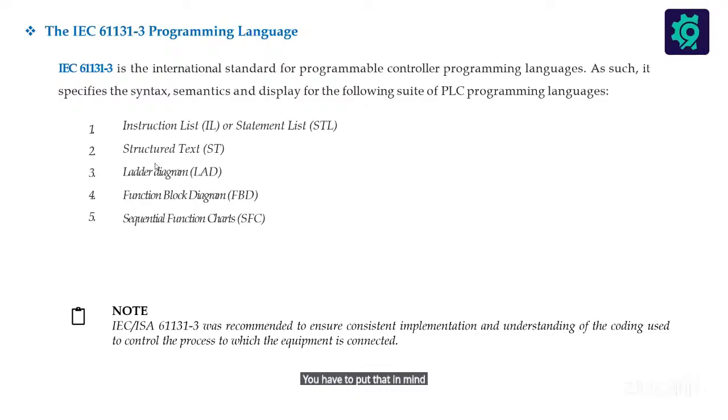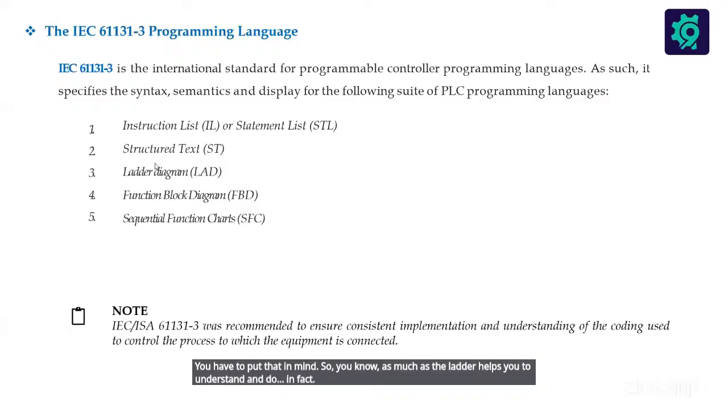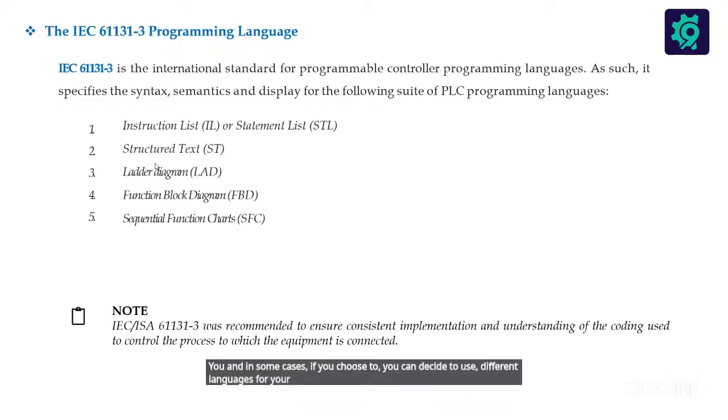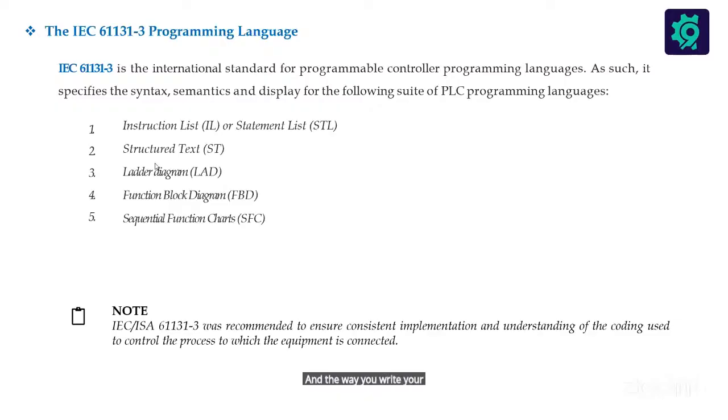So, in as much as the ladder helps you to understand and do, in fact, you can do a lot with the ladder diagram without even having to work with the instruction list or structured text. And in some cases, if you choose to, you can decide to use different languages for your program. So you can write a particular FB with ladder, write another one with instruction list, write another one with structured text. You can be creative in the way you write your program.